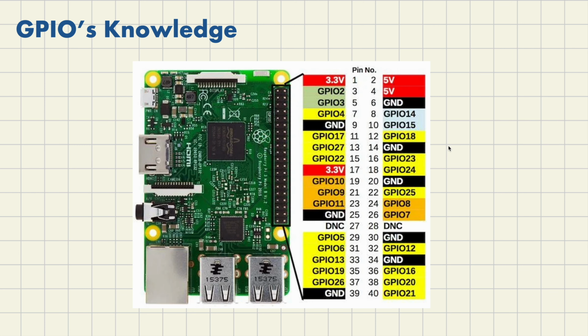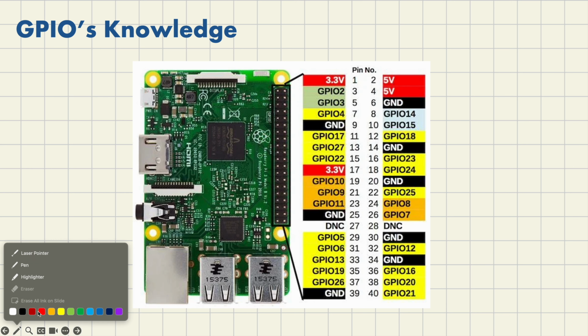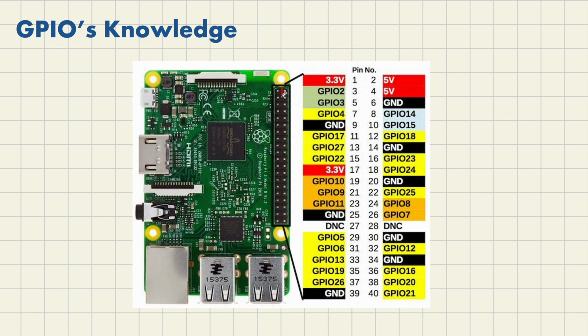The port numbers and the functionalities don't change. The picture is of a Raspberry Pi 4 module. I couldn't find a Pi 5 one with the memory mappings, but yeah, this is fine. The important terminals to remember are the 3.3 volts, ground, and 5 volts terminals. These are very important to learn first, and all the rest of the GPIOs are configurable.